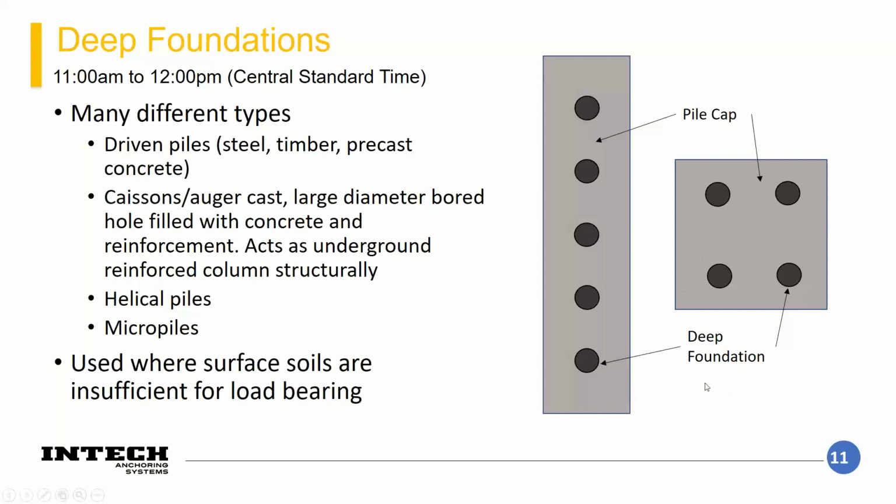So now we'll look at deep foundations. Whenever you have a project where the loads from the structure are too high to be resisted by the soil, or you have highly compressible soils where excess settlement or differential settlement is a concern, that's whenever you switch to a deep foundation option. And there are many different types of deep foundations.